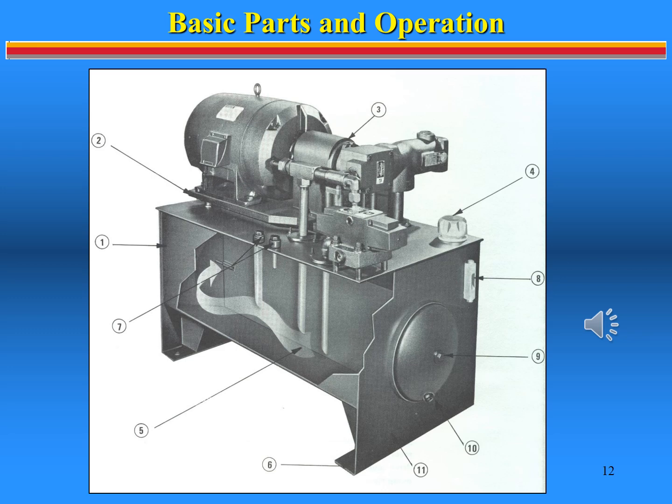The filler breather cap at number 4 allows for adding of fluid, escape or entry of air, and filtration of air. The baffle at number 5 forces return fluid to travel further before returning to the suction to ensure greater fallout of contamination and escape of air. The reservoir legs at number 6 allow for the mounting and circulation of air. Additional return and drain lines at number 7 allow for machine modifications.